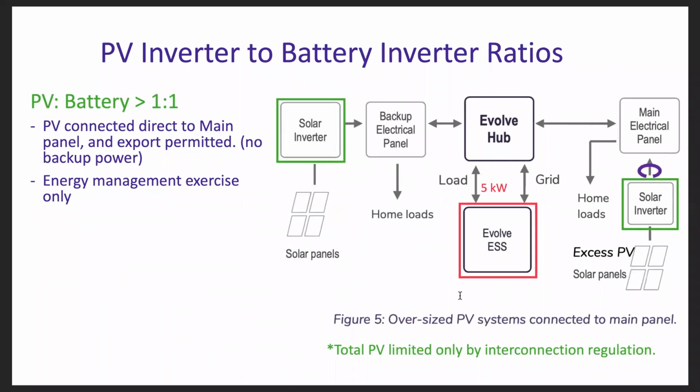And for systems that have quite a bit more than that 5 kW or even 6 kW of PV, it'll be required to split that up if you don't have a way to curtail the PV when you go to off-grid mode. If you work with SolarEdge inverters, we can use up to a 7.6 kW SolarEdge inverter here because the SolarEdge has a method of controlling its output through a PRI, or power reduction interface.